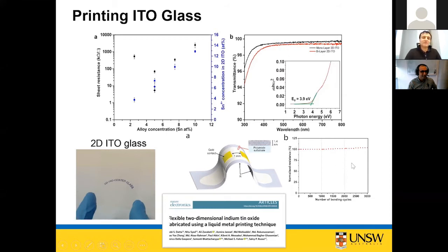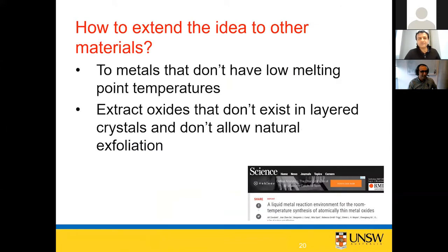Another advantage is that they are super transparent. The absorption of ITO glass is more than 5–6%. Here, absorption is almost only 1% at two layers with a very similar conductivity. So very soon, I think, and another thing that I didn't put in this slide is that it's a new crystal of ITO. So basically three discoveries in one paper. And very likely it will change the concepts that we have about transparent conductive oxide of the future.